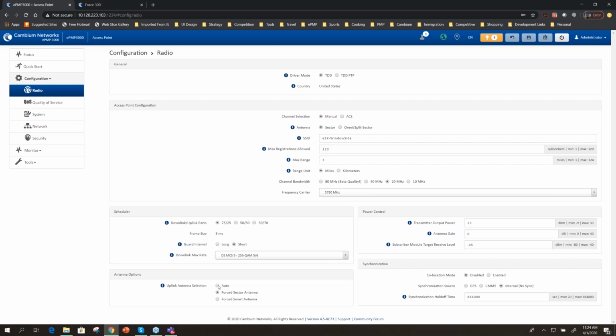That means it was a wide azimuth antenna, which meant that in the uplink, it also picked up a lot of interference. Therefore, a beam steering antenna with a 20 to 25 degree beam width really helped you in mitigating uplink interference.